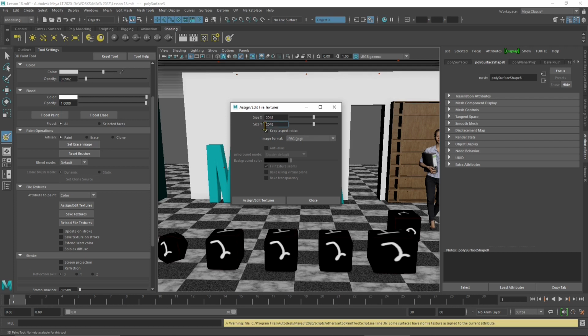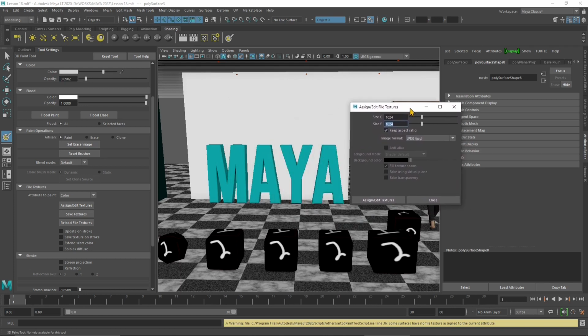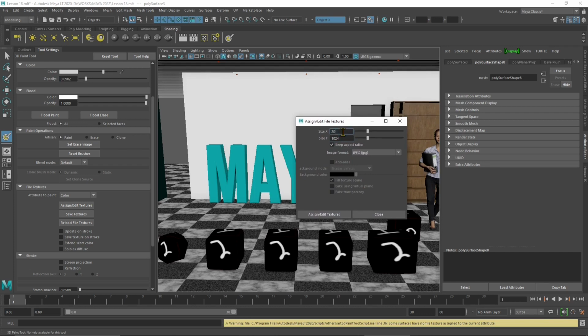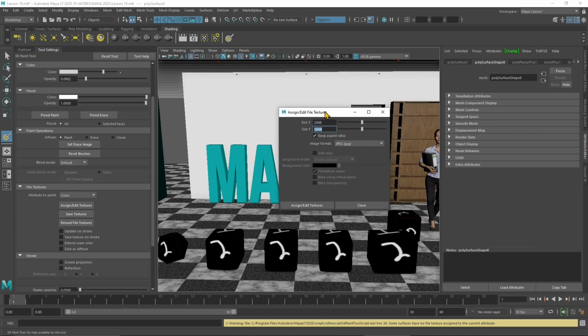And this is also what we talked about in the previous video. So also when you search for textures, be careful on the sizing, not too big, not too small. It has to be optimized for what you have to do. So if it's an unwrap texture like this one, a single texture, you can bump this up to 4096. But if it is a tileable or tiling texture, you can drop that down perhaps to 1024 or 512.